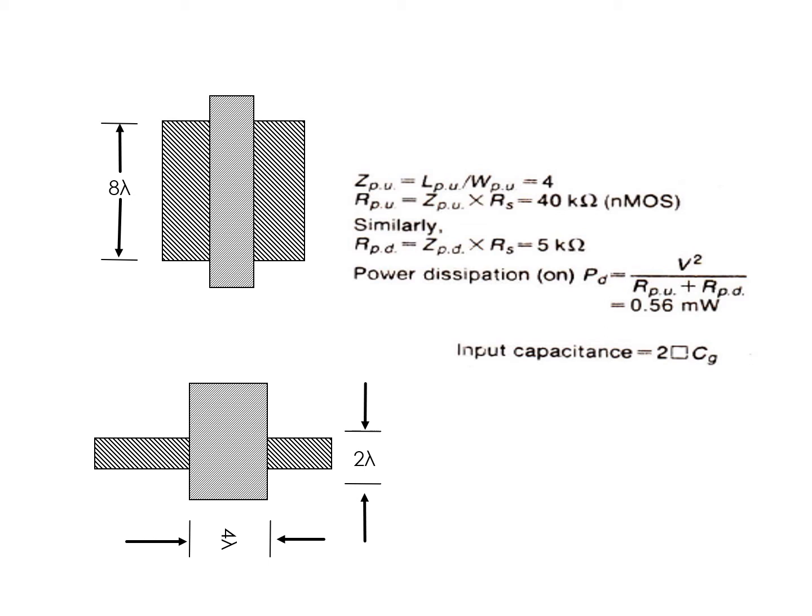So the CMOS inverter carries no static current, and hence there won't be any power dissipation unless the inverter performs in the switching mode. So the CMOS circuit should have no dissipation problem, but it is difficult for you to develop a CMOS circuit without any power dissipation.